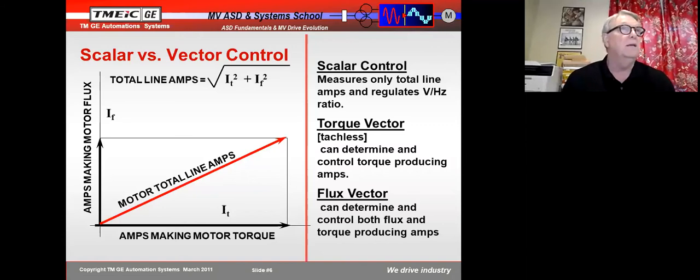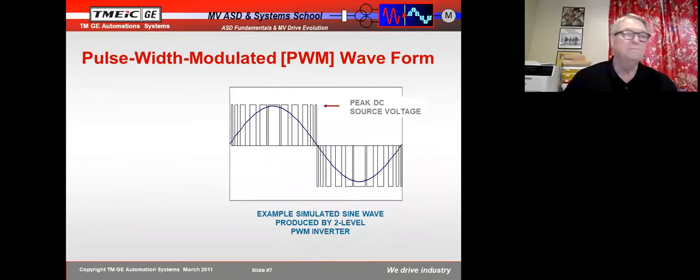In 30 seconds or so, it stops and it says motor tuned. And that's it. It's very sophisticated, very complicated, but you don't need to know anything about it because it all is done by the drive. Medium voltage drives are the same, except that we tend to take a little more care and will tune them at different load conditions. But it's the same idea.